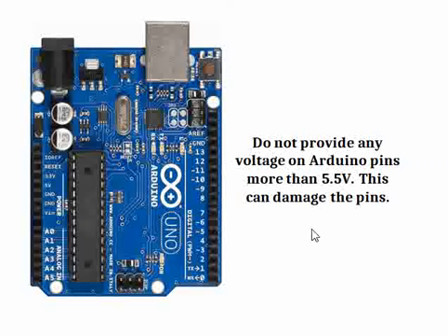So while using the Arduino board, we cannot use it in whatever way we want. There are some restrictions on the levels that can be applied to Arduino. For example, on the Arduino pins, you cannot give any voltage more than 5.5 volts. That is the absolute maximum. So you have to limit the voltage to 5 volts, but it can go up to 5.5 volts. And even on a per pin basis, you cannot give more than 6 volts absolute maximum.